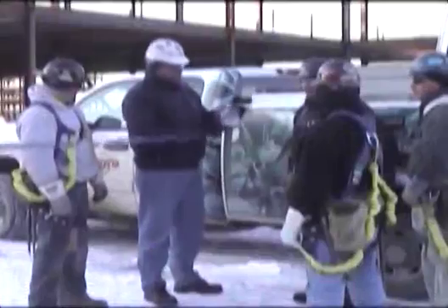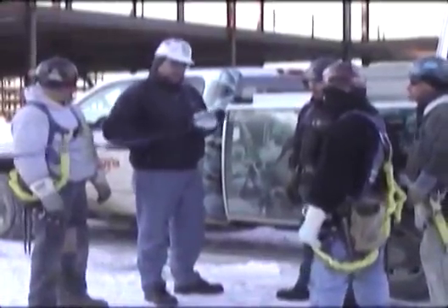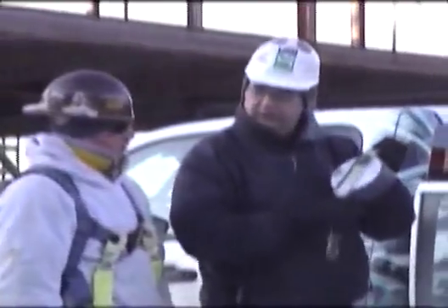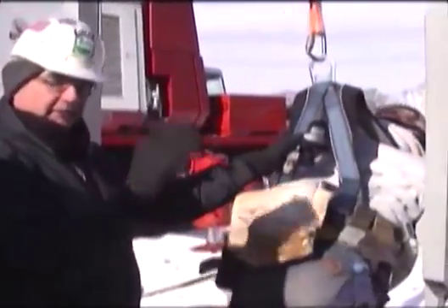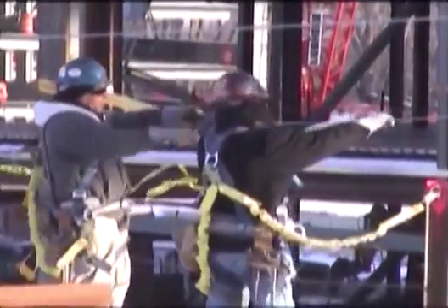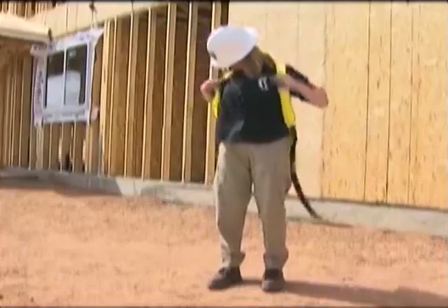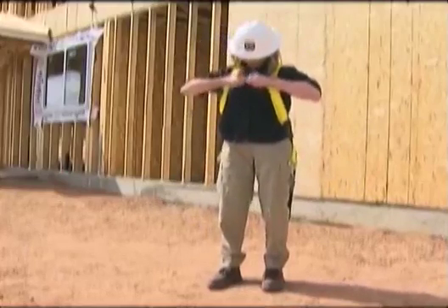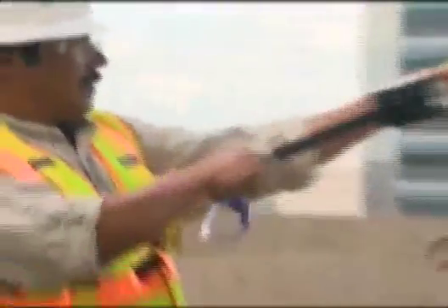An employer is required to provide fall protection training to their workers who might be exposed to fall hazards. Employees must be trained to recognize fall hazards and in procedures to follow to minimize hazards. The training must be performed by a competent person who knows the nature of fall hazards in the work area, correct procedures for assembling, maintaining, disassembly, and inspection of fall protection systems to be used, the proper use and operation of all fall protection devices, including fall restraint devices, arresting devices, and any other device that minimizes fall hazards.